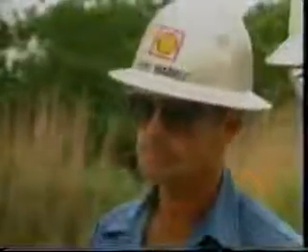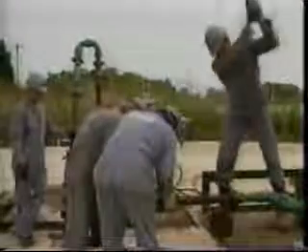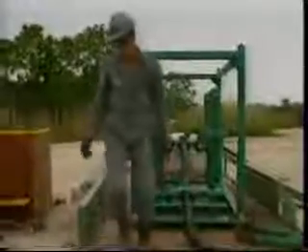Because this reservoir is partially depleted, the fracture gradient has changed from the initial fracture gradient of 0.6 psi per foot. The current fracture gradient, and then the maximum treating pressure, can be determined in several ways.